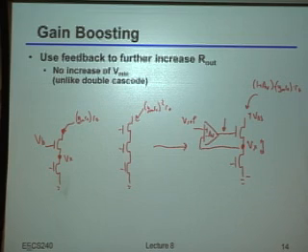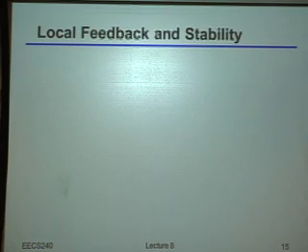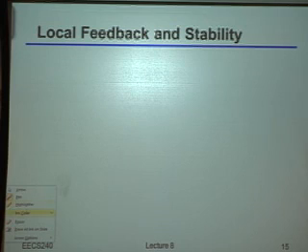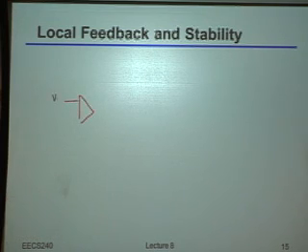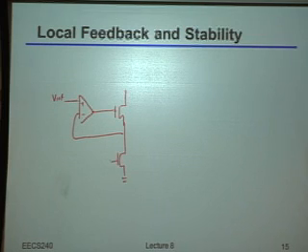So if I'm worried about the stability of that feedback loop, because indeed I've now got a feedback loop in my circuit, what's the first thing I need to think about, or how will I analyze whether or not this thing is going to be stable? I'm going to redraw the circuit while you answer that question. What is it I need to worry about? How am I going to figure out whether or not this whole thing is going to be stable? Yeah, I basically have to analyze what the poles are, and perhaps what the zeros are as well.